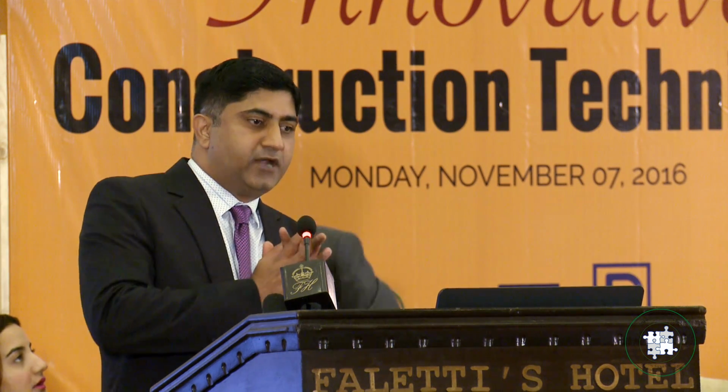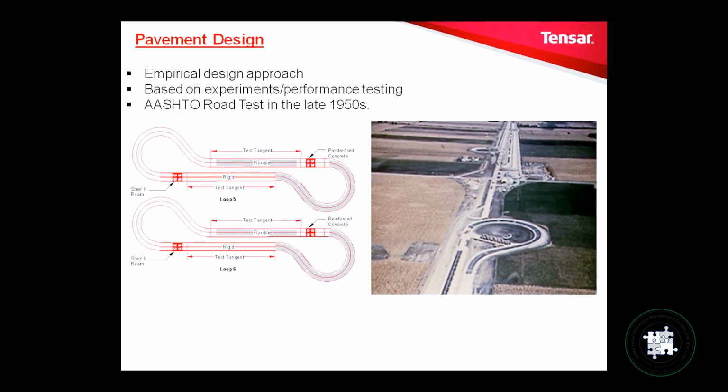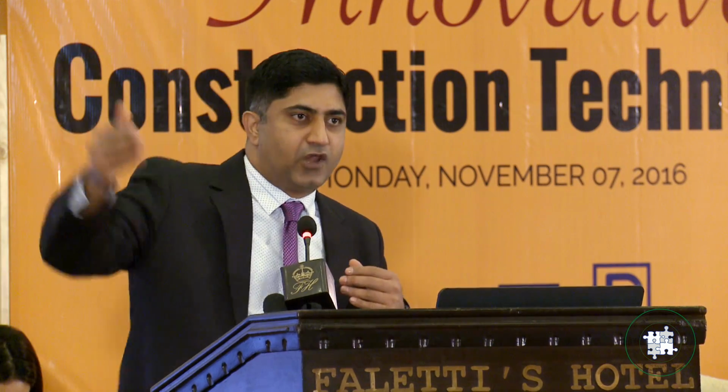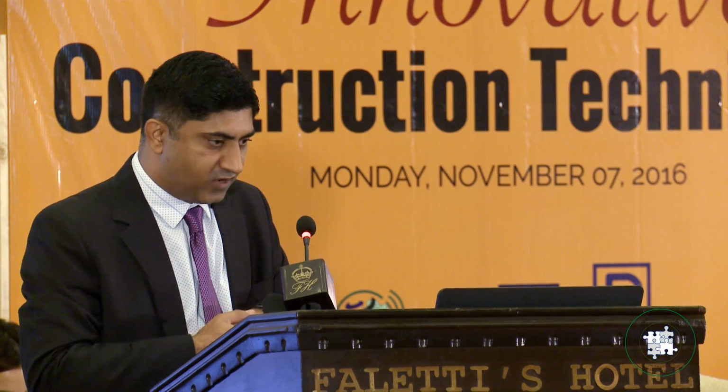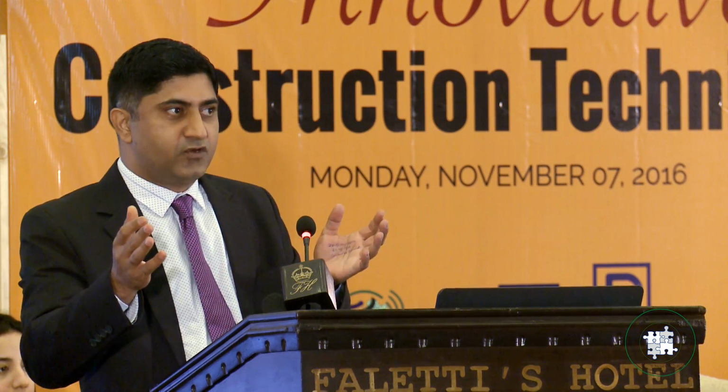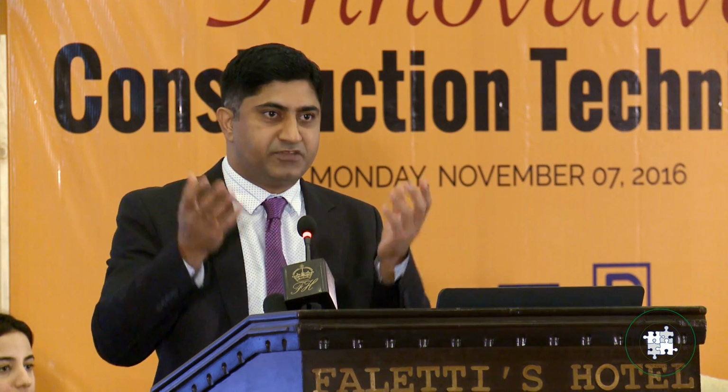I'll quickly go through it. Pavement design, we know this is all empirical design. Originally, the AASHTO was based on the 1952 road test carried out in the USA. It went through a lot of modification, and eventually we have got the latest AASHTO codes. So the point is, AASHTO code and all other design codes all over the world are empirical, which means they are based on experiments.